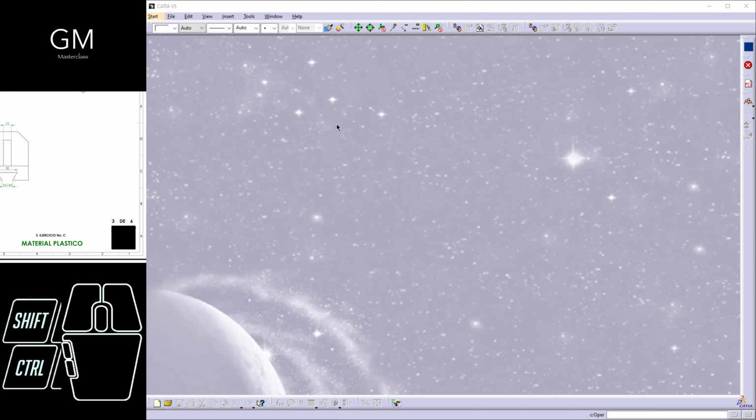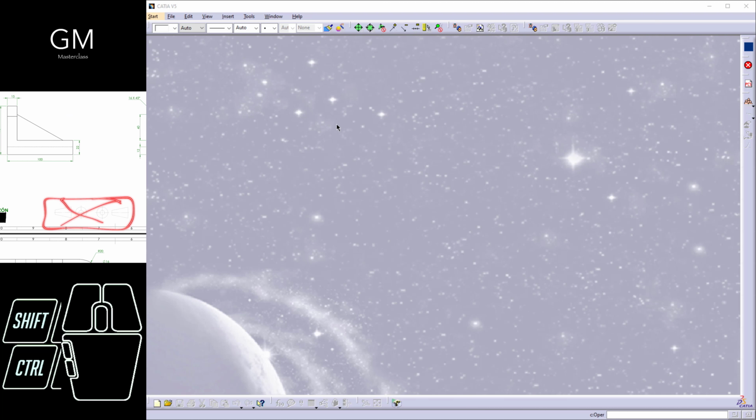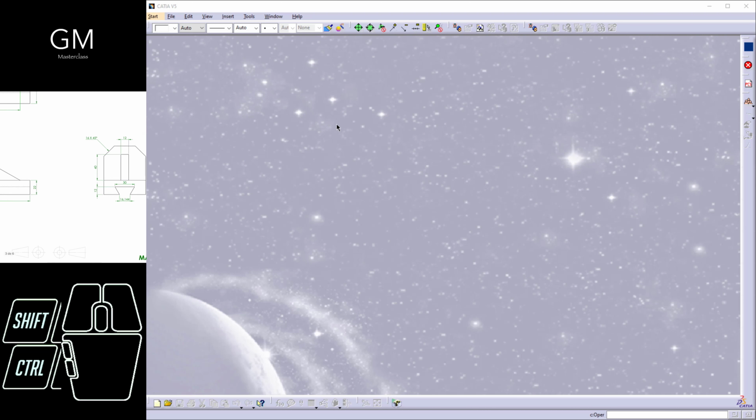Since I cannot find anything, and this means actually nothing, as well as this, I don't know why this person put this right here. This means nothing. We're going to start using millimeters, right? This is a rule, and if you cannot find information about anything within the engineering draw, you can assume that these are millimeters, right?